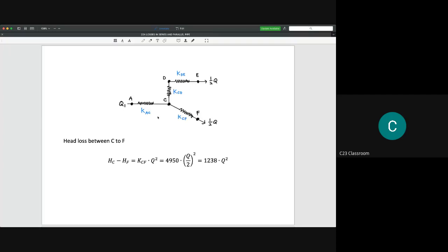As you know, if you want to calculate by using the Bernoulli equation, as we learned in fluid mechanics 1, we need to do it as two calculations, because we only can compare the energy from A with the energy at F, and also the energy at A with the energy at E. It is not appropriate to compare the energy at E to the energy at F, because there is no flow between E and F. Please make some revision about how to use the Bernoulli equation.